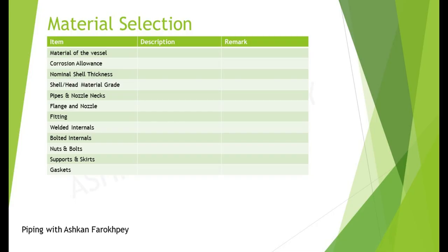Secondly, the corrosion allowance of the selected material shall be specified. And finally, we need to specify further requirements of the material. The rest are items such as HIC, SSC, impact, PWHT, or other features that are required for being assured about the material. Finally, the exact ASTM grade for plates, pipes, forging, and fittings needs to be clarified from ASME B31.3, Table A1 for construction engineers.